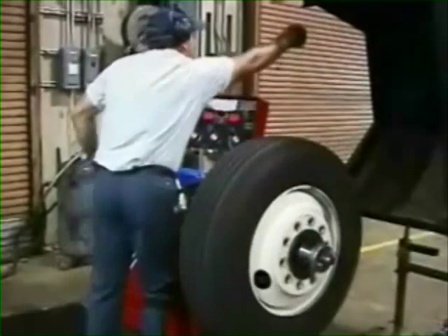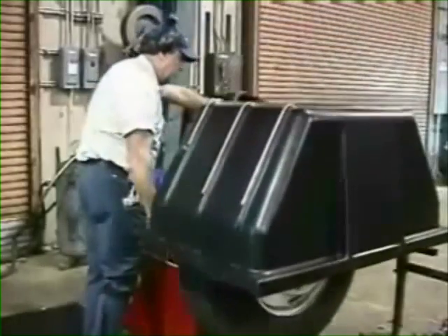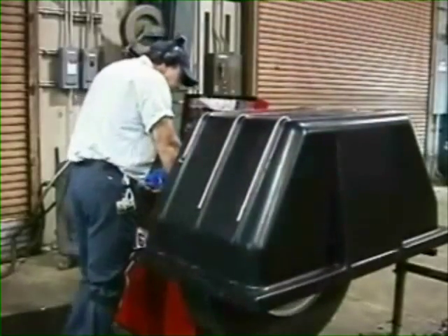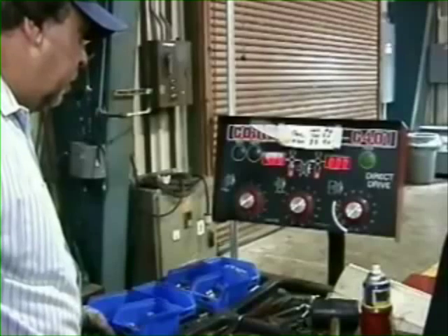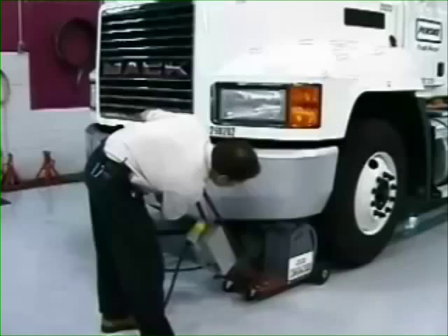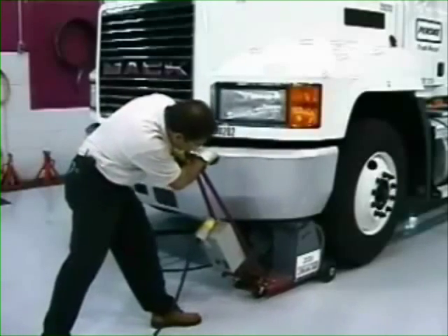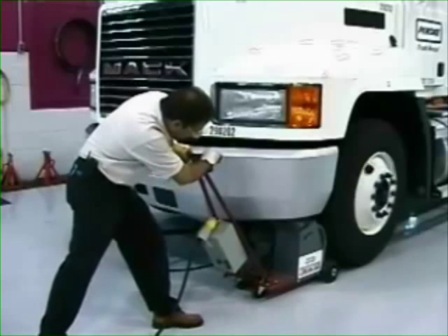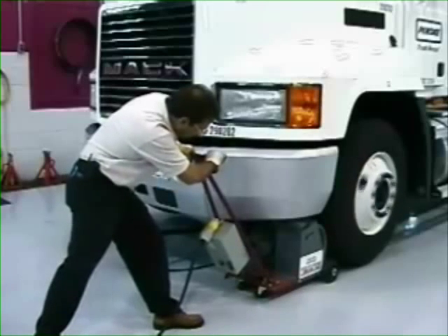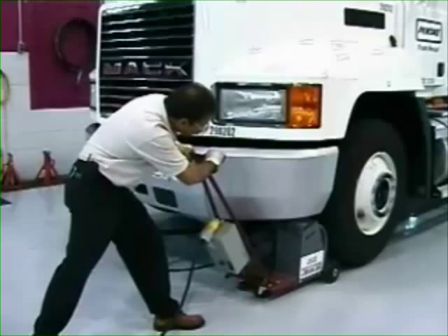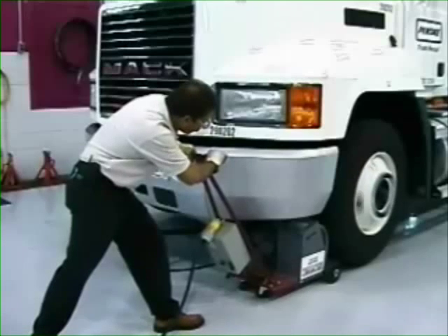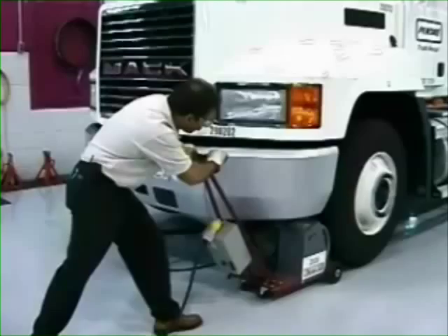A tire and wheel assembly which has been dynamically computer balanced will be in better balance than an assembly which has been balanced with an on-vehicle balancer. With an on-vehicle balancer, the tire will produce the equivalent of a static balance even while rotating. Mounting a balanced assembly on an unbalanced hub will still leave an out-of-balance situation.